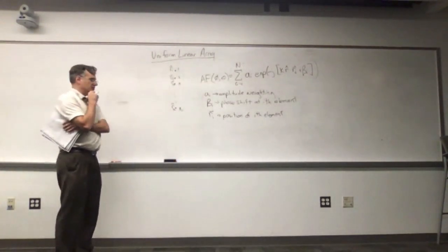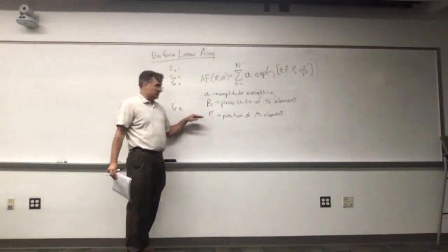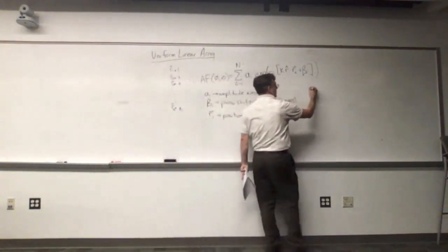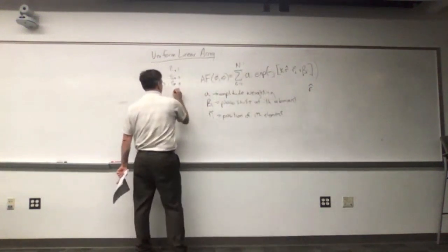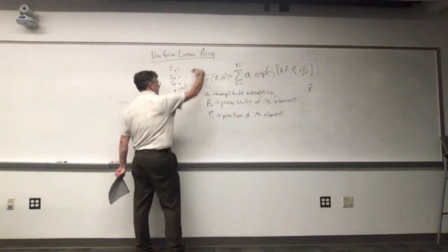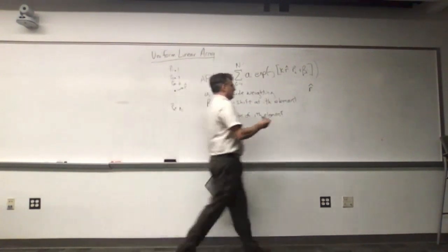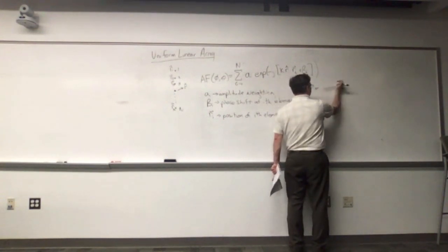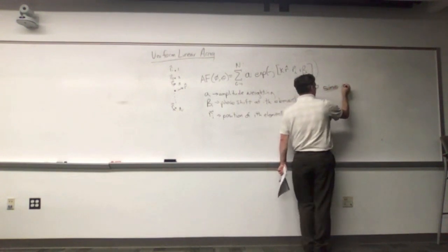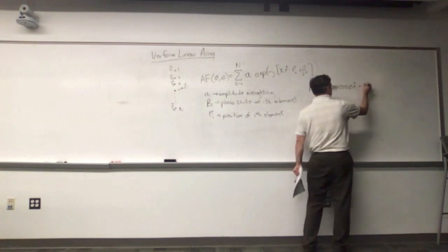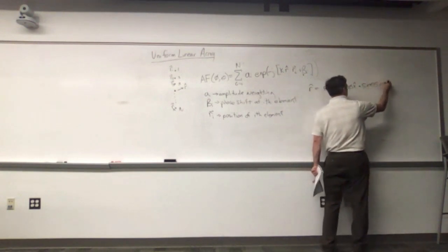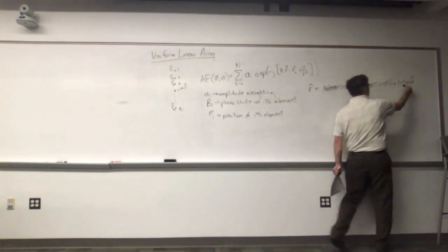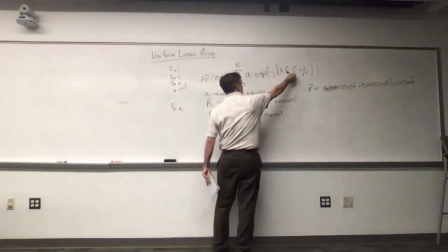Now, there are a couple things in here we haven't introduced yet. First of all, this is a general expression. I can put those anywhere in three-dimensional space. And because r hat, recall, is the unit vector that points in the direction of my point of observation, hopefully in the far field. Remember, in spherical coordinates, that's going to be sine theta, cosine phi, stick it on the x hat, sine theta, sine phi, stick it on the y hat, plus cosine theta.